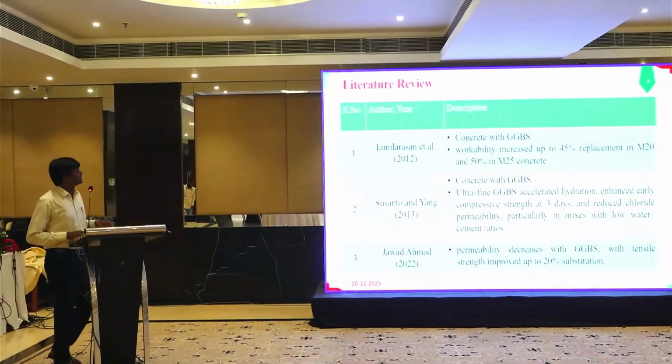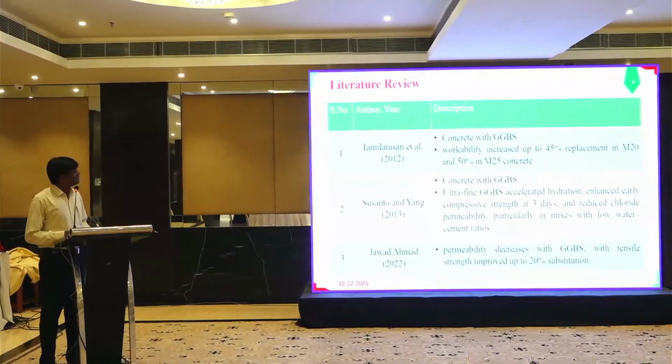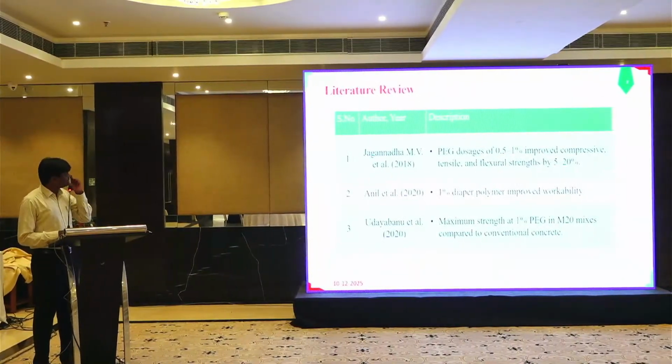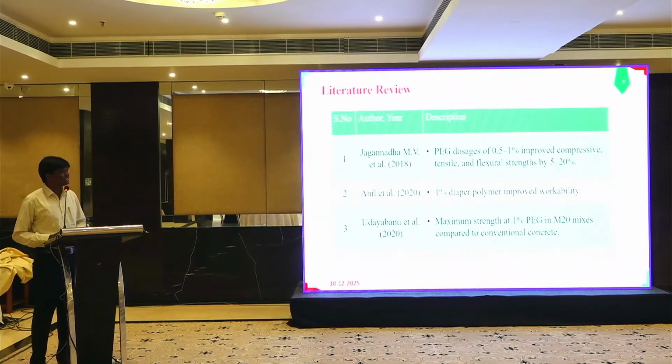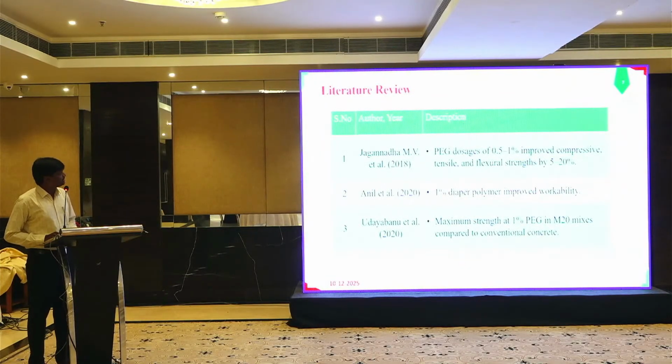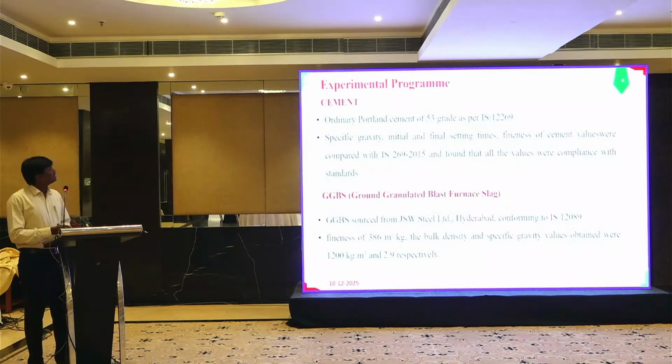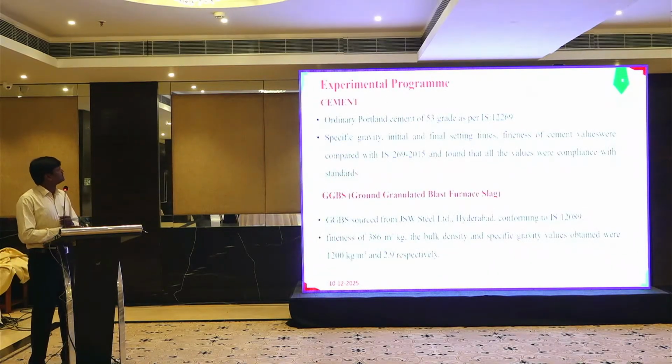Some of them are on GGBS, and these are the literature reviews on PEG, that is self-curing concrete, PEG dosage. In my experimental program, these are the materials used: ordinary Portland cement, that is 53 grade cement, and GGBS,